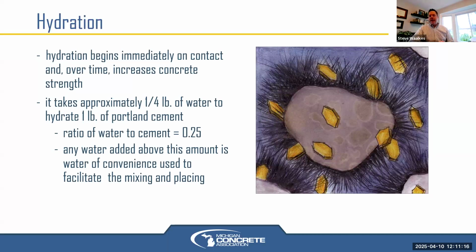So with adequate amounts of water, theoretically, the cement would need a water cement ratio of about 0.25, but that is not a workable concrete mixture. So we typically see water cement ratios higher than that, up to usually 0.45, maybe 0.5 max, and usually in the 0.4 to 0.45 range to have adequate workability and constructability, but also minimal shrinkage and adequate strength.